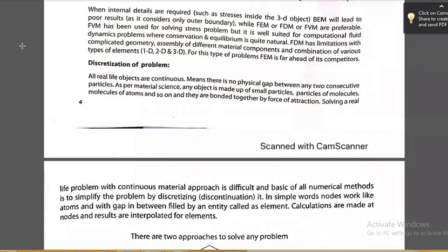Degree of freedom is nothing but the number of minimum parameters needed to specify the system. If your object is in space, then we can say that this object has 6 degrees of freedom. What would be these 6 degrees of freedom? First three are in a linear direction: in x direction, in y direction, and in z direction. These are three linear coordinates, as well as three angular coordinates. Angular means movement about x, about y, and about z. So what do 6 parameters mean?